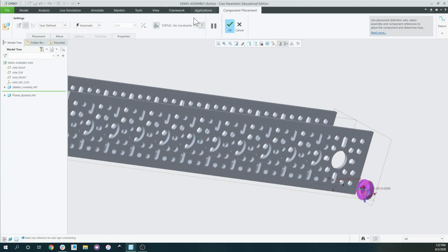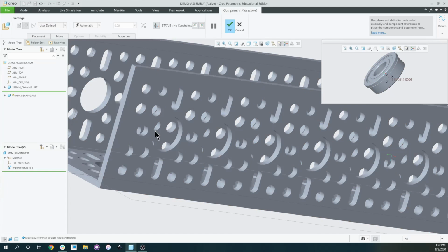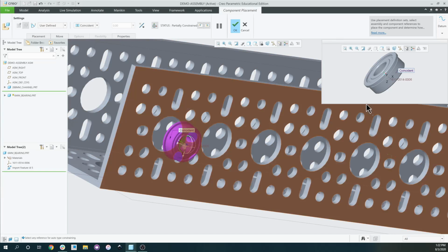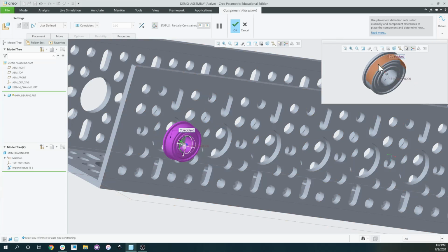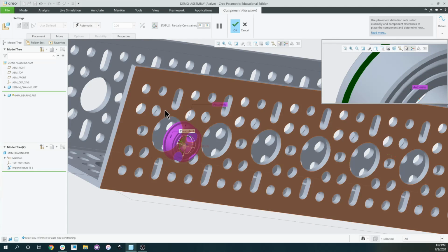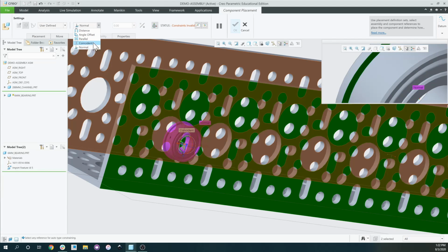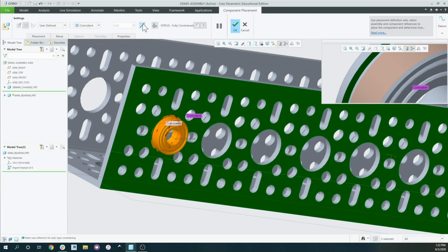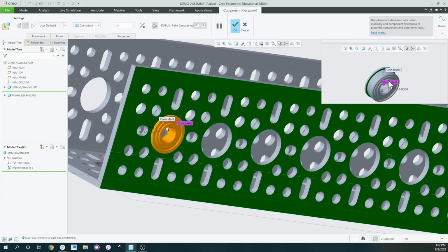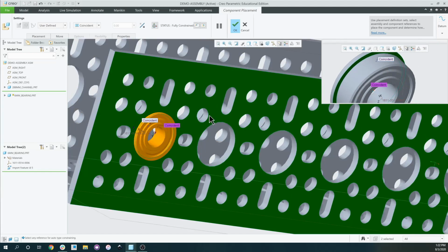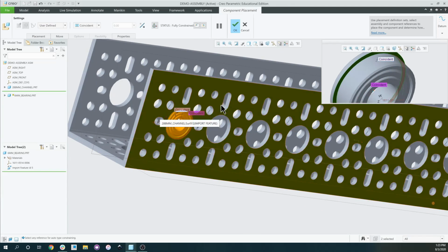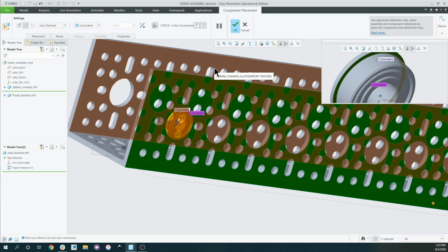So one super cool tool that Creo actually has is this button right here. If you click on it, it'll actually show you a close-up view of the part where you can actually select things. So if I want it in this hole, I would select the ring there, and then I can just click here and it moves itself. I don't have to scroll back and forth like I was previously. And I can do that all around. So it makes it super easy to do things in a much more efficient manner, because I can actually view my bearing in the top right corner and click on the actual channel in the bottom left. So that is that part view I mentioned earlier.